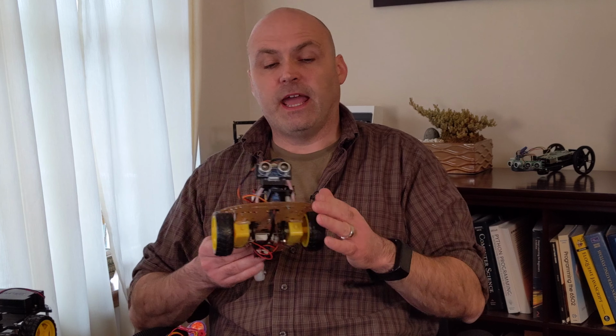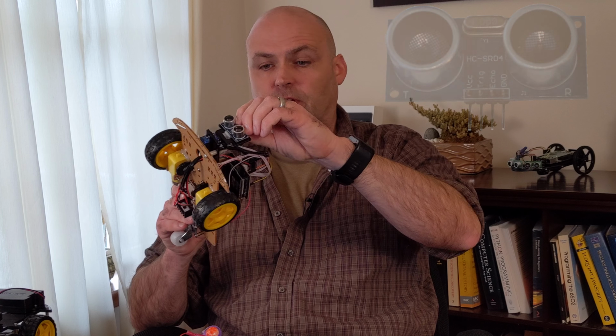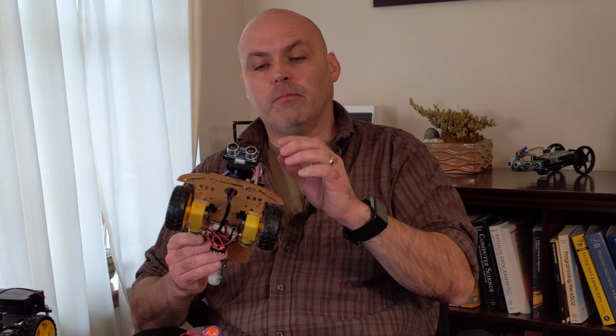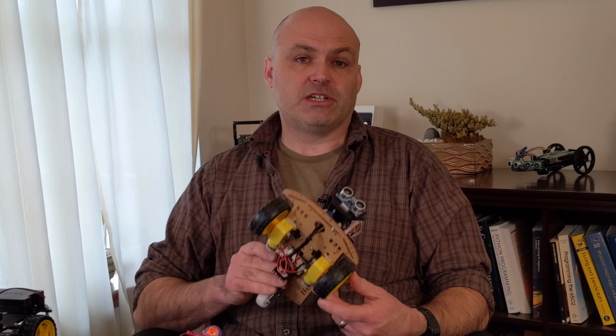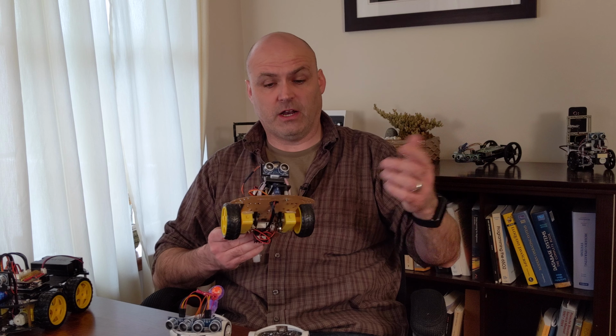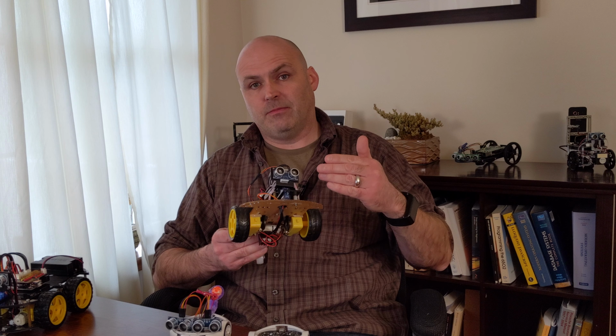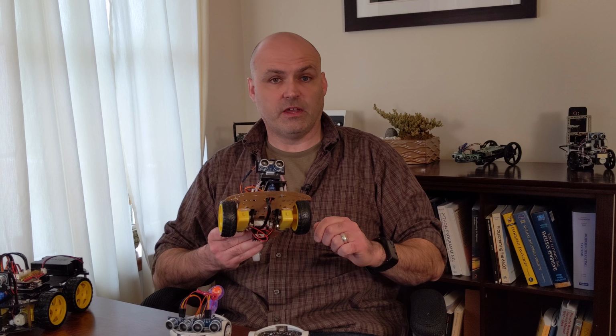Another trait that these robots share, except this one because we haven't put it on this one yet, is that they have ultrasonic sensors. Some have more than one, and some have one here that's maybe mounted on a servo, and we're going to talk about that more in later videos. But these sensors are going to be the eyes, but actually more specifically the ear of our robot. So our robots are going to operate much like a bat. These sensors emit a high frequency sound, hence the ultrasonic, which then can bounce off objects and be heard by the same device.